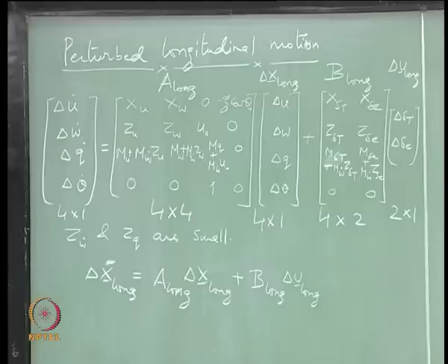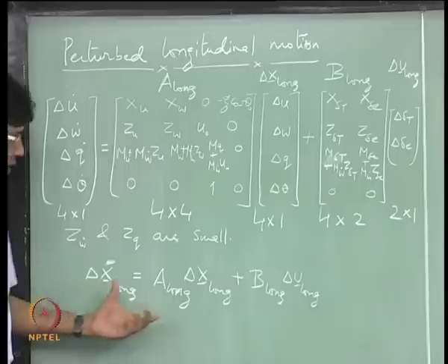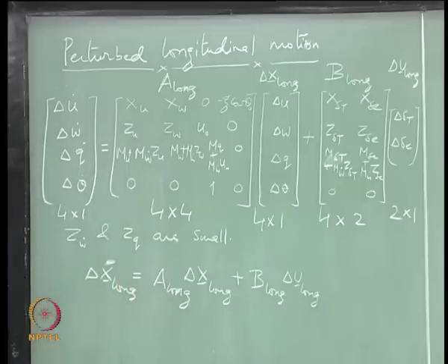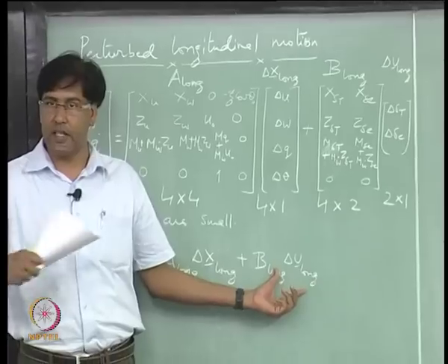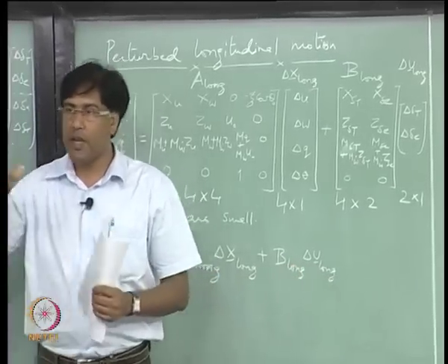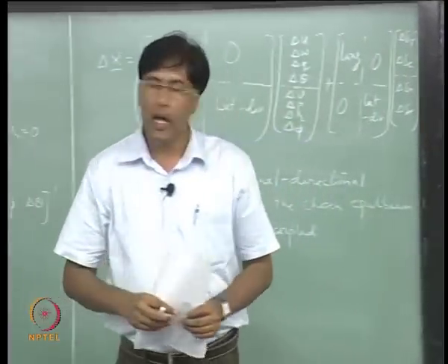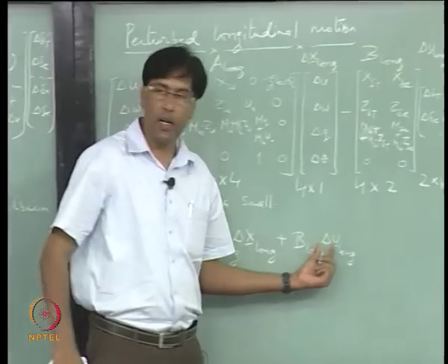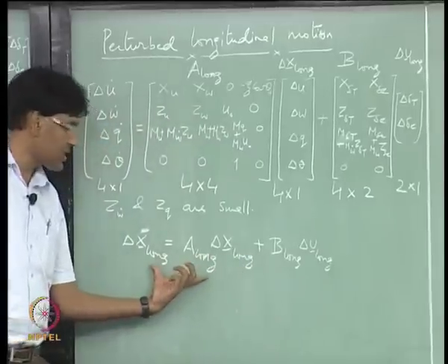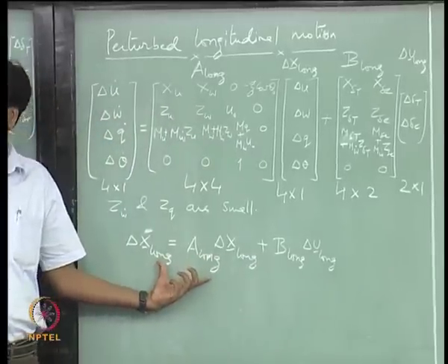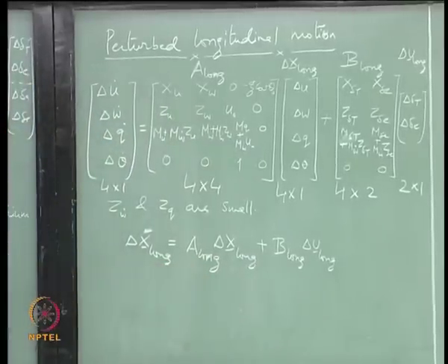Right. So, I want to look at the stability first. To study stability, dynamic stability, you assume that this delta u is fixed, is 0, right. I am trimmed at some flying condition and I do not allow this delta u to change, then all I will get by solving this part is the free response of the aircraft to perturbations, right.